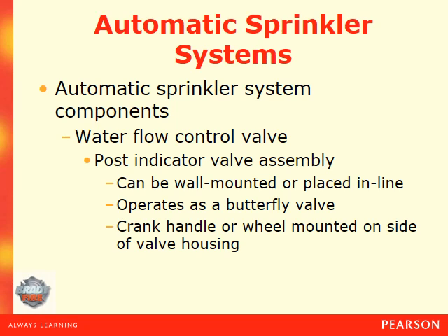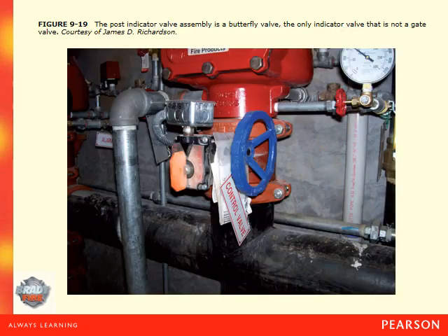Post indicator valve assembly. It can be wall mounted or placed in line. It operates as a butterfly valve, with a crank handle or wheel mounted on the side of the valve housing, which allows for opening and closing. Here's an example here.